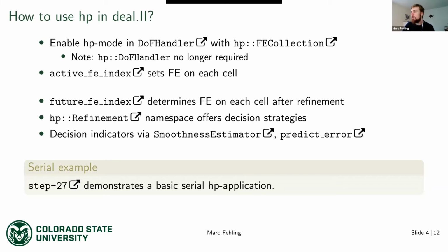Just as a side note, deal.II veterans will know that there was a class hp DoFHandler. This is no longer required. You can use the normal DoFHandler, and actually the hp DoFHandler doesn't exist anymore. It's just an alias for the original DoFHandler class.